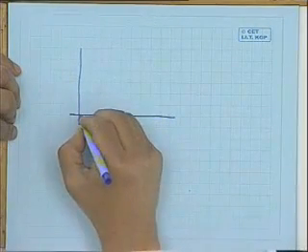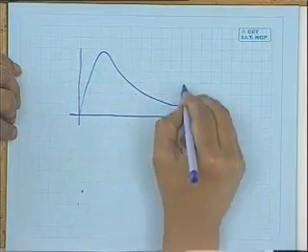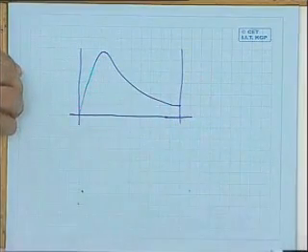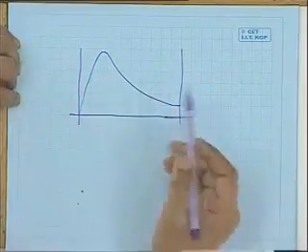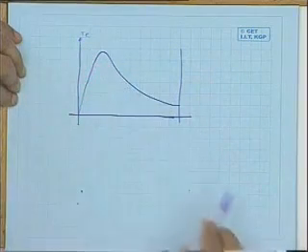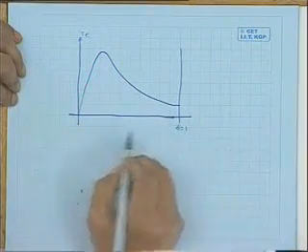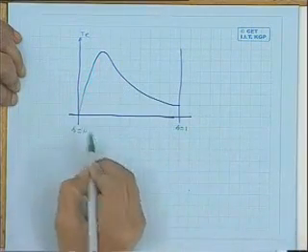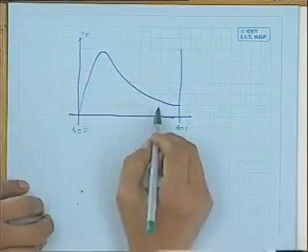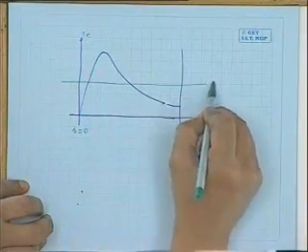For example, you now consider this is the torque slip characteristics. Okay, machine has been started like that. This is the torque axis and this is the slip axis, s equal to 1. You should not make any mistake here, that is, often students make S equal to 1 and S equal to 0 the wrong way round.